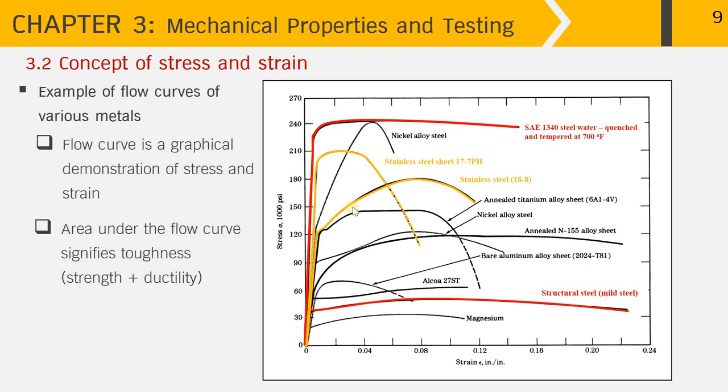Here are another group of ferrous metal. Stainless steel differs from steel by adding chromium and nickel to make different microstructures. But here you still have high strength in both types, a little bit different strain. But both make these two stainless steel different from the previous steels. They can offer corrosion resistance, which is much superior than the normal steel. Now, let's move on to a non-ferrous alloy. Here you see the green curves showing the stress strain or the flow curves of their aluminum alloy sheet.